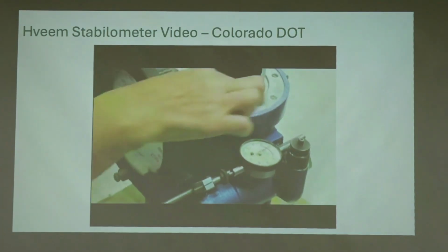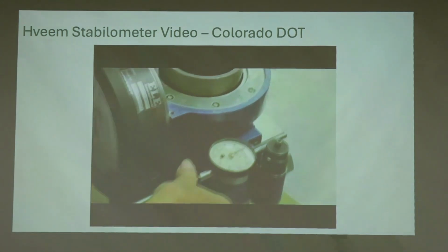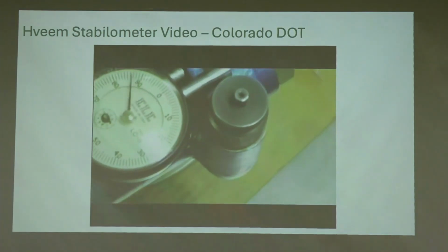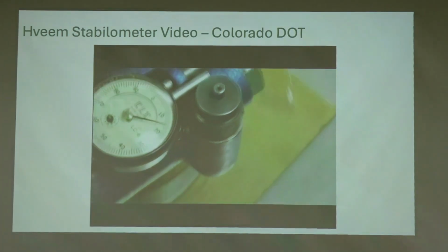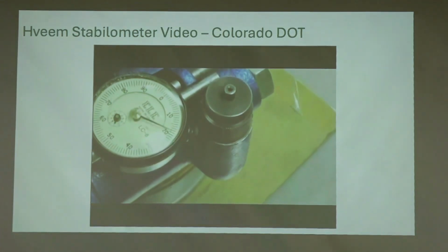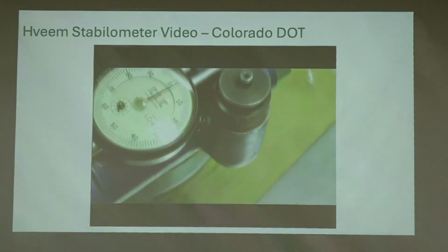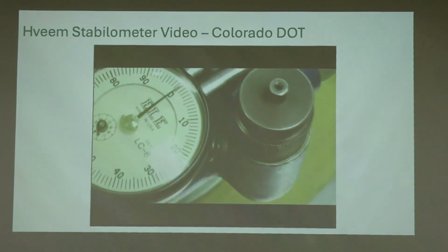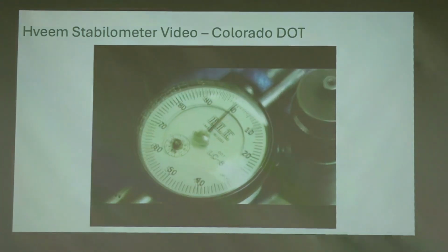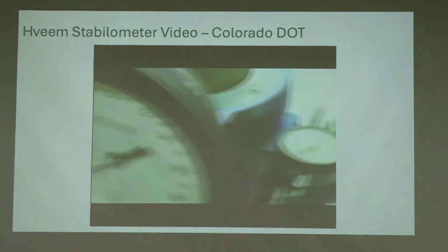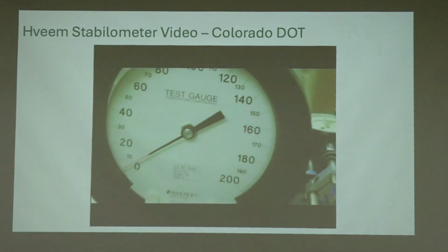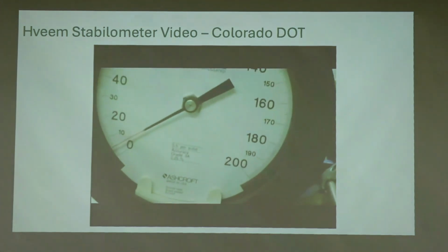Once you have both of those dials set, you're going to be turning the horizontal pressure handle out exactly 2 turns, watching the turns displacement dial. So this is all related to calibration. You should not worry about that much. The initial part. So if the needle is a little above the 5 psi, you're going to have to let air out. If it's below, you're going to have to let a little air in.